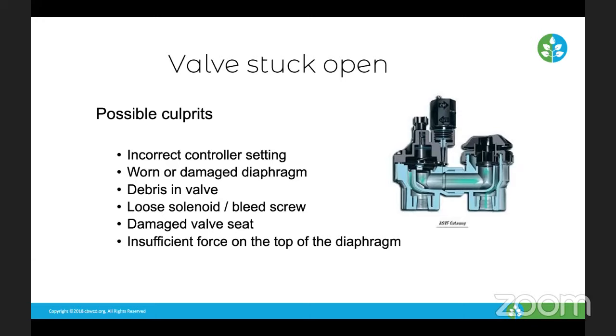So the culprits for this: incorrect controller settings. Again, controllers could be an issue. I've seen it where something went haywire on one zone and the controller is constantly sending power to the valve unknowingly. Worn or damaged diaphragm. Again, that's that center part. They do wear over time, especially if the valves are inactive for a long time. They can get very stiff, and then when you try to turn them on, you run into issues like that.